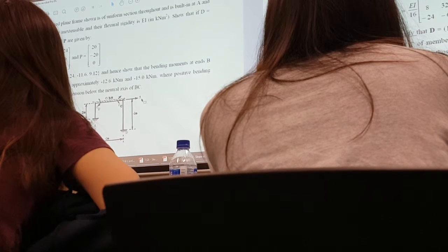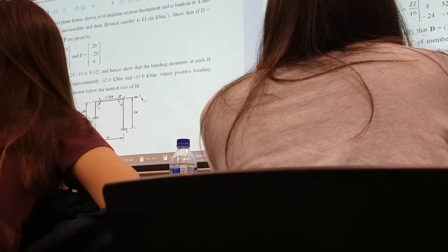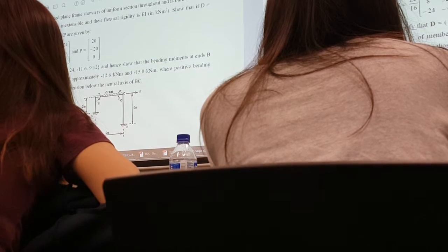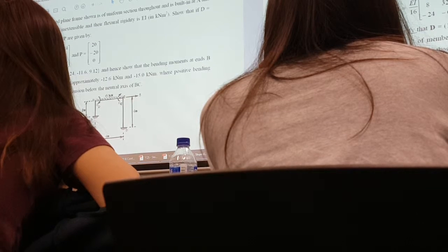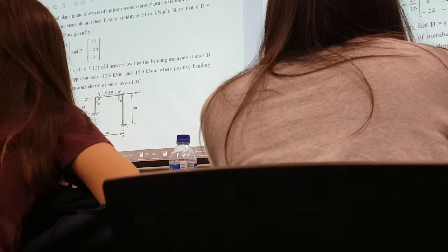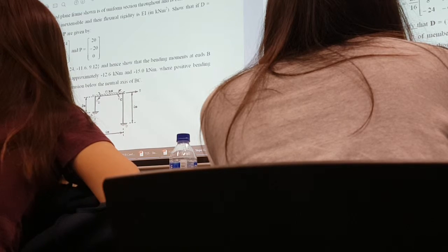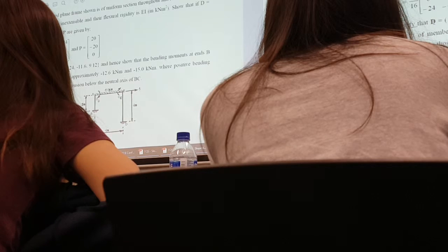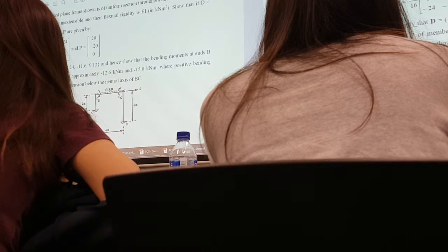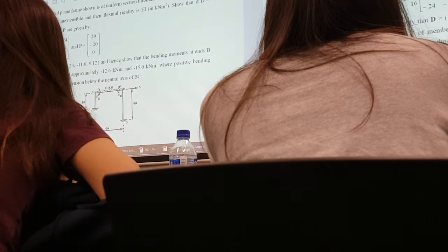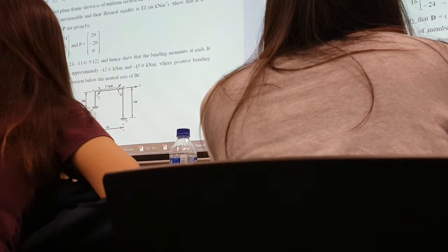After that, you have to break it down and find the individual member equations, right? Then from there, you have to form the stiffness matrix. And from the stiffness matrix, you then have to calculate what's the P. And P has to be equal to PA minus PF. And once you have that, you will be able to solve the equation to find out all the various displacements of theta B, theta C, and delta. Then you can find the moments at B and C, respectively.